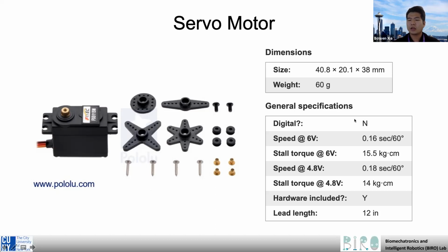And there will also be 1 output for the angle signal from the integrated position sensor, which is the white one. It is common that servo motors have an integrated position sensor, but not all servo motors allow access to that angle signal. So sometimes there are only 3 wires connected to the servo motor. The servo motor's integrated control system can already perform very basic, low-level control. For example, move to the desired angle when a command is sent on the control wire.